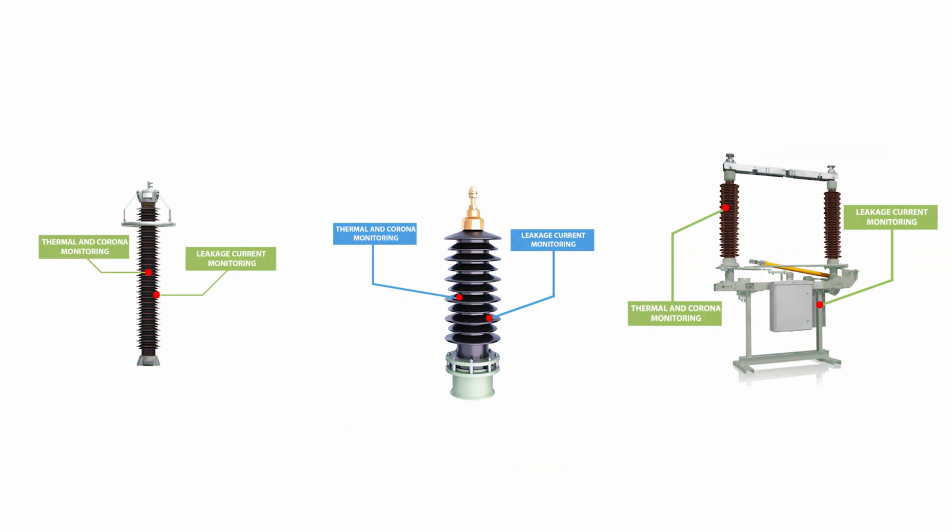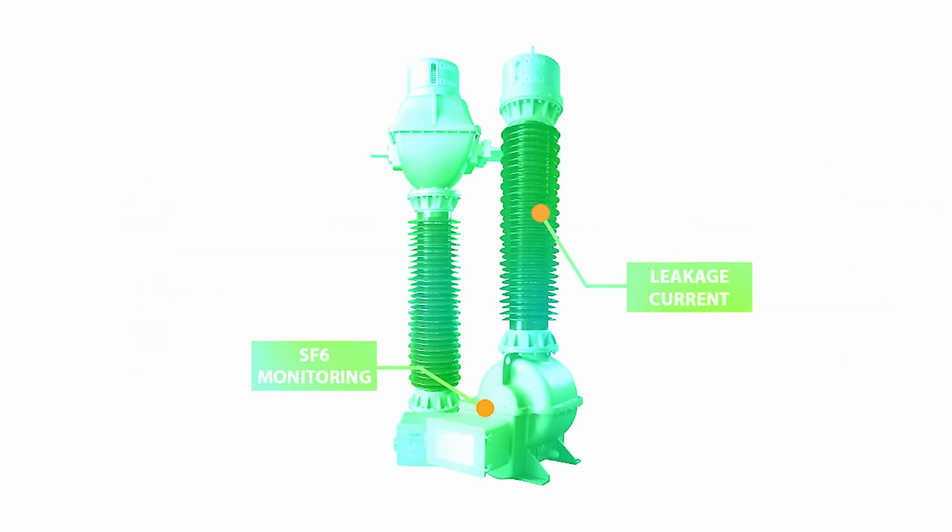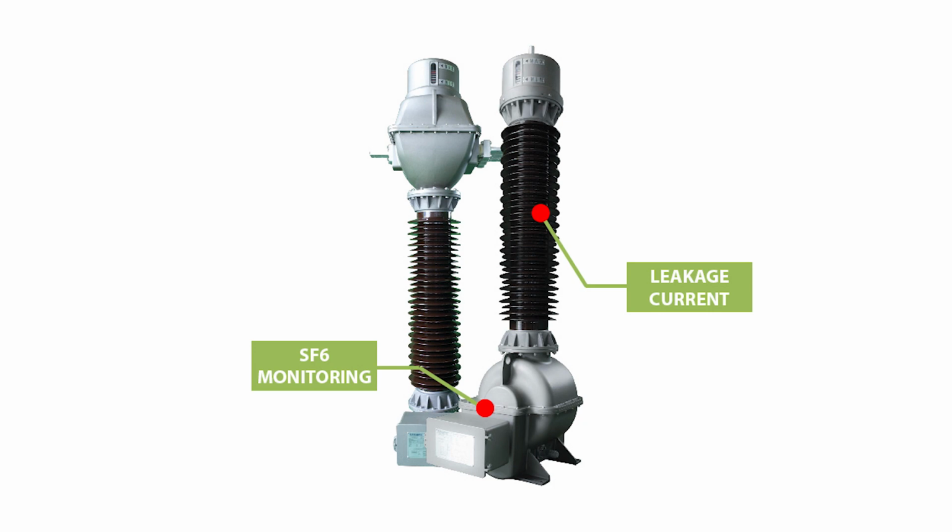Our monitoring solution for surge arresters, disconnecting switch and overhead lines can monitor leakage current monitoring, harmonics analysis and insulation, temperature, and corona wirelessly. For instrument transformers we can monitor insulation media SF6 quality or oil DGA monitoring, leakage current, temperature and corona monitoring.